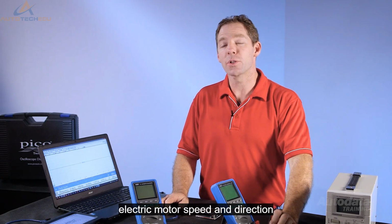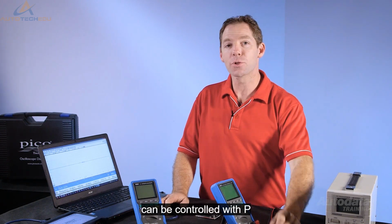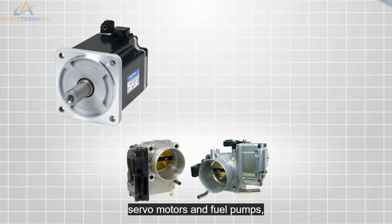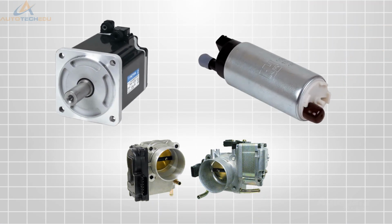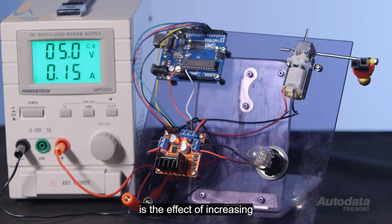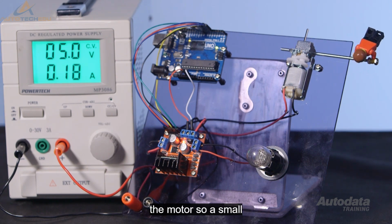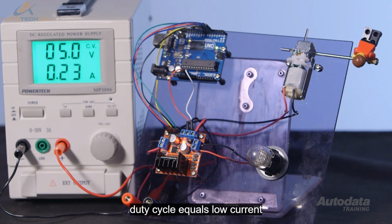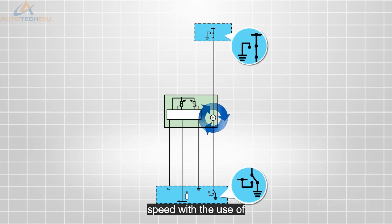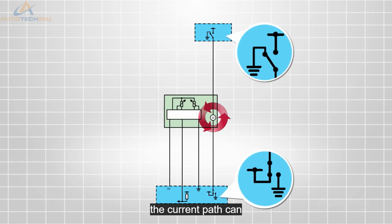Permanent magnet type electric motor speed and direction can be controlled with PWM as well. We've seen this in throttle valves, servo motors and fuel pumps. An electric motor's speed can be altered by changing the duty cycle control. This is the effect of increasing or decreasing current flow to the motor. So a small duty cycle equals low current flow and therefore low motor speed. With the use of bidirectional drivers in a control module, the current path can be reversed. This will change the motor direction.